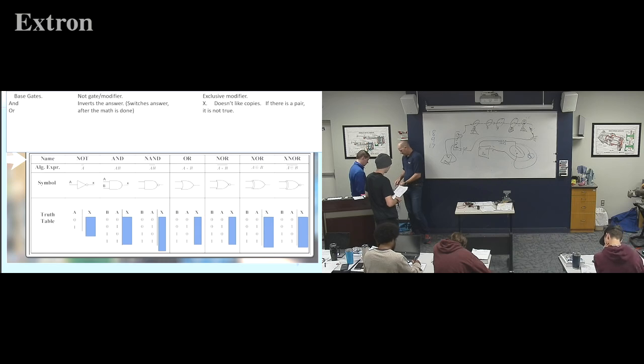But because there's no amperage, if you were to draw the resistance triangles for Ohm's law on these, this one's going to have 0 amps. The resistance doesn't change, right? Because the resistance didn't change, and we know the amperage is 0, that means it's going to be 0 volts then. So without current, that's how the voltage changes.